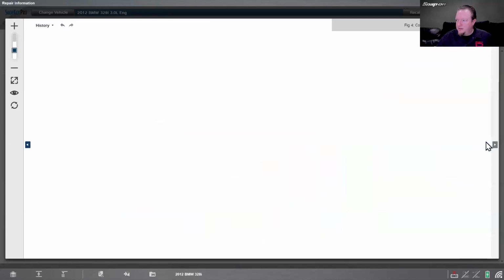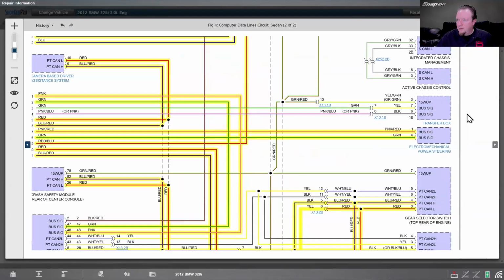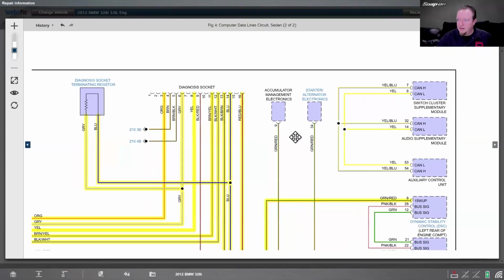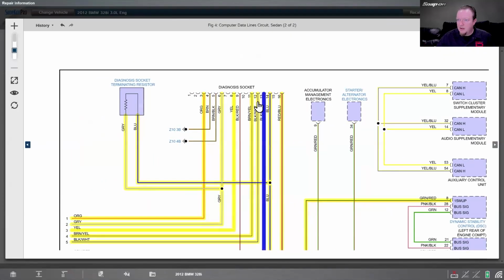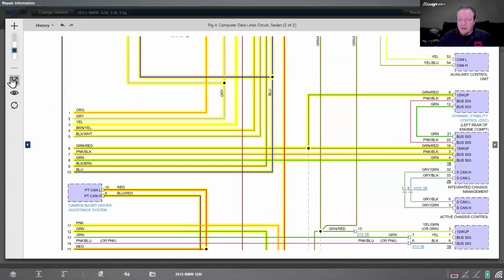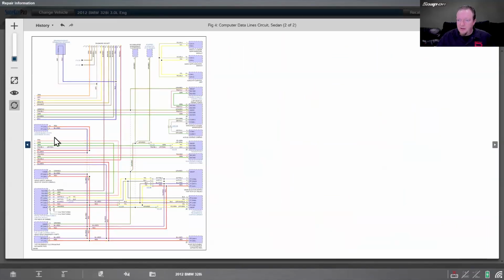And then if I go across the way, that's going to bring us to the, where is it? There it is, diagnostic connector right there, 16-pin. This one actually has a terminating resistor in there between 6 and 14 for the CAN bus. Interesting. You don't usually see that called out on many vehicles.